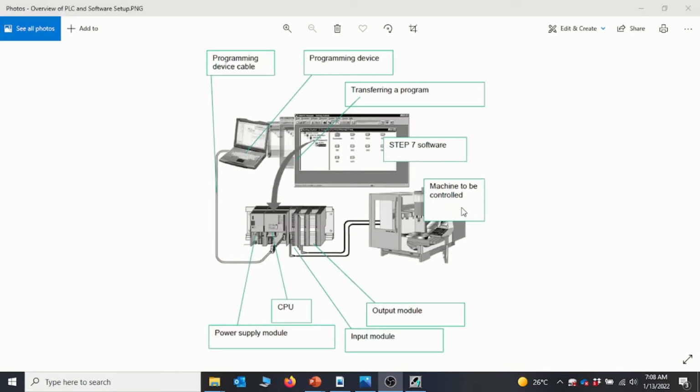Okay, so now after the addressing, let's have a look at the typical setup of a Siemens PLC project. So we have the PLC right here, which is the 300 station, and the arrangement of the modules on the rack is basically fixed, and you don't need to change the arrangement position. When we have a look at how we set up hardware, we will go into details of how exactly it's done. But as it stands now, it's just a review of how setup is done in the Siemens PLC.